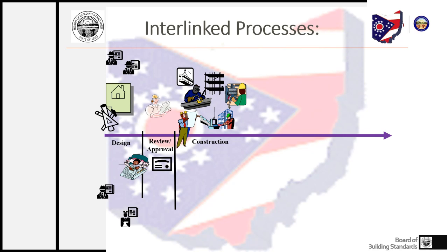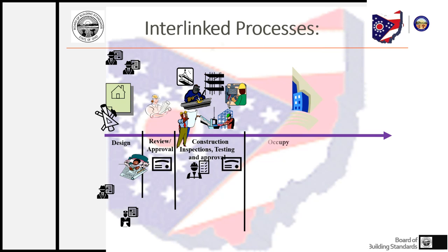He starts going through that, but he's also been tasked with the responsibility to ask for inspections by the building department at those required times where he's supposed to have the inspections done, the building inspected. So the inspector goes out, he checks off his list. When all of the required inspections are done in a satisfactory manner, that inspector reports back to the building official. If the building official is in concurrence, he issues a certificate of occupancy, and that is the line in the sand that says, okay, Mr. Owner, it's okay for you to safely occupy your building.